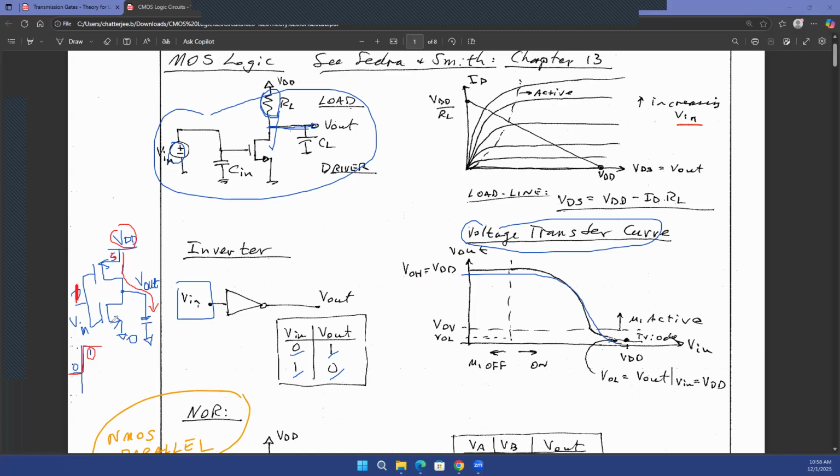So this is exactly the opposite. Now your PMOS is off, but your NMOS is on. And if your NMOS is on, NMOS can conduct current, but PMOS will not conduct current. So the current path from VDD to output has turned off. And in its place, the current path from output through the NMOS to ground has turned on. So the capacitor will discharge through this path.